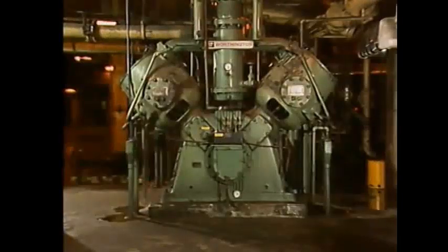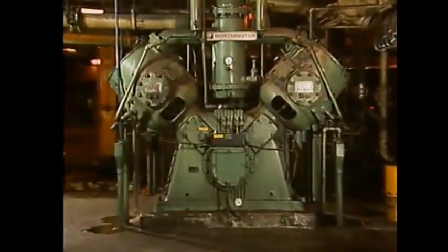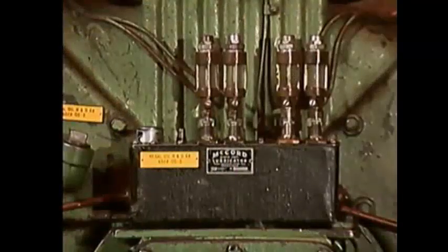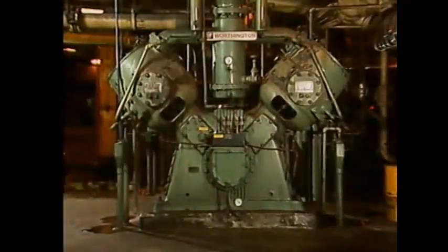Another important job that must be performed for a compressor is cooling. When a gas is compressed, heat is produced. This heat can cause two major problems. First, most compressors are oil lubricated, and excess heat can break down oil, causing it to lose its lubricating characteristics. If this occurs, the compressor's internal components can be severely damaged.